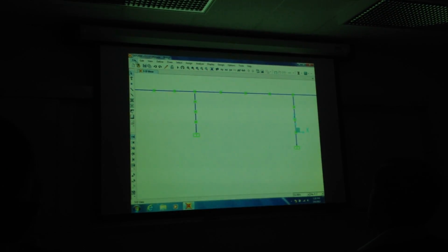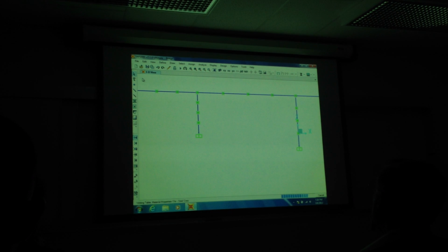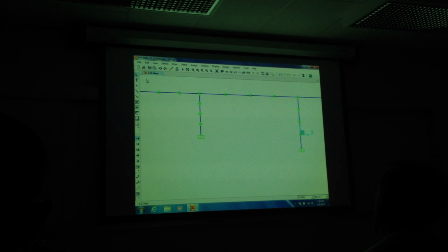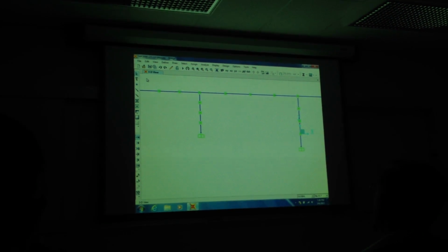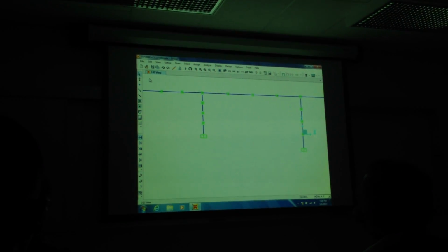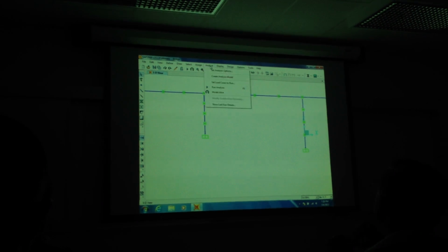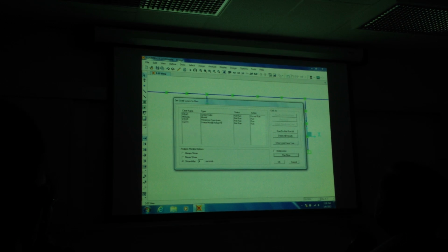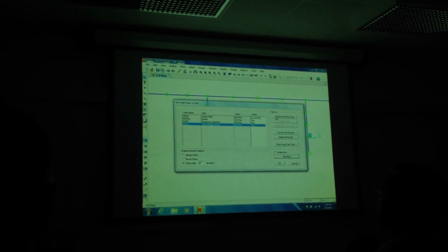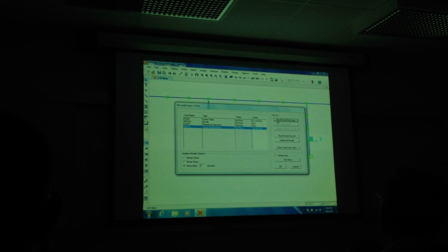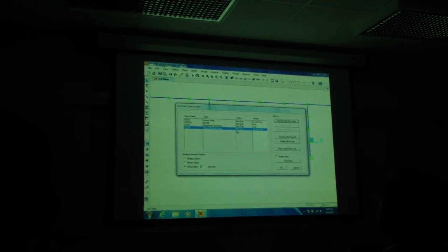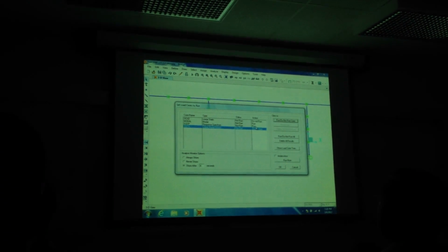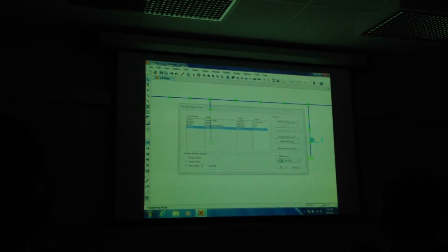So we should be able to save it and then run this analysis, okay? And then we can compare this to the time history analysis for the same earthquake. And you get a sense, do we get back the same results or very different? So let's say analyze, run analysis, and I'm going to say, see the response spectrum, I'm going to say don't run that case. So we're not going to run the time history. We have to run the modal analysis because the response spectrum is going to use that in the response spectrum. So run that.